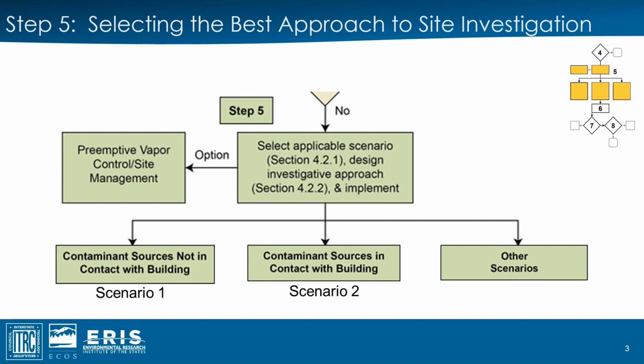And B, subsurface vapor samples are going to reflect the effects of biodegradation in the vadose zone. The latter can be significant. For example, a published evaluation of US EPA's petroleum vapor intrusion database showed that concentrations of benzene in soil gas were biodegraded below risk-based screening levels in over 60% of the vapor samples collected within just a foot of an LNAPL source.